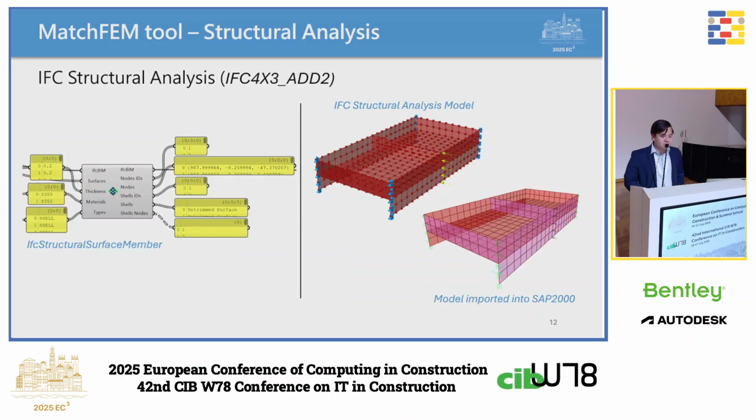And last but not least, we have the structural analysis data layer. It's possible to generate structural analysis models following the IFC schema. We can leverage the geometric capabilities of Grasshopper to mesh surfaces and generate finite shell elements. This is a resulting structural analysis model for a steel profile. And these IFC models can be imported in any commercial software that allows the import of this data into the system, for instance, SAP 2000.